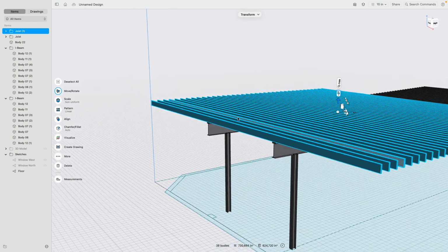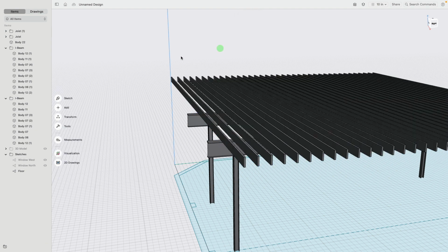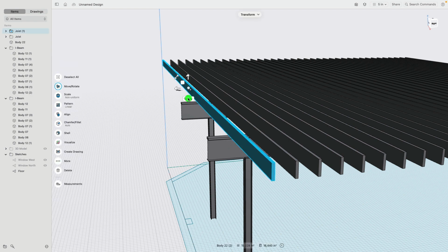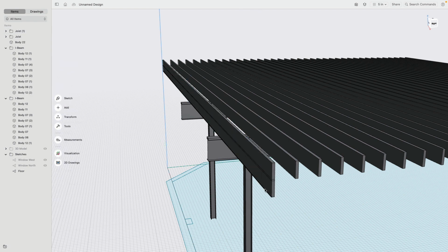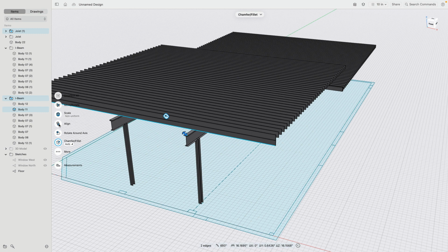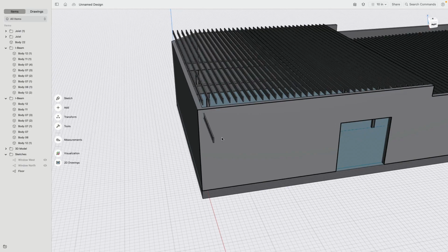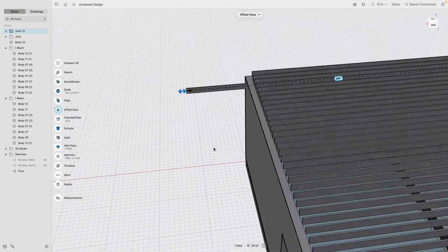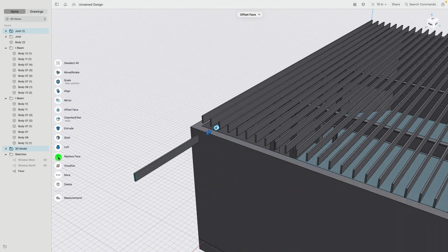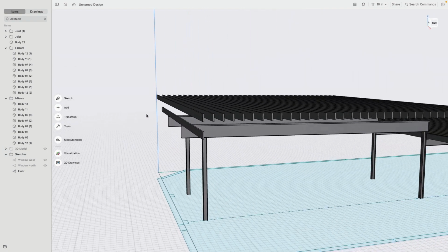Now, how do we perfectly position this? So I will do the following little trick here. There we are. Thank you. So now I will say from this one, make me a copy. Thank you. And then this copy I would like to align to this edge. There we are. Very good. Then I will show the wall because this is wrong. And shift click these two faces, replace. There we are. Then I can turn off this piece again.